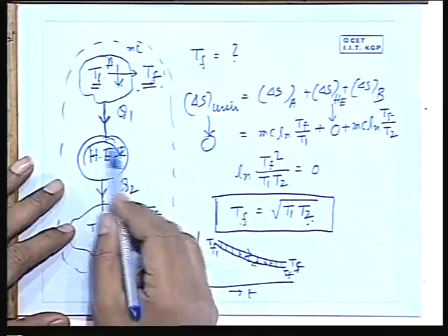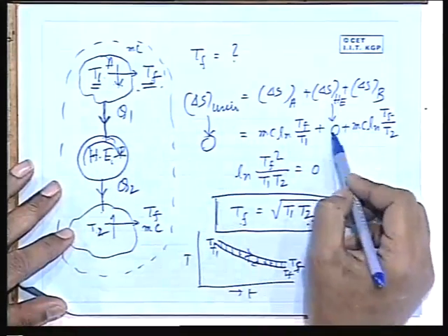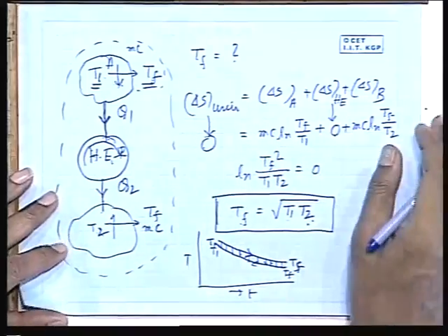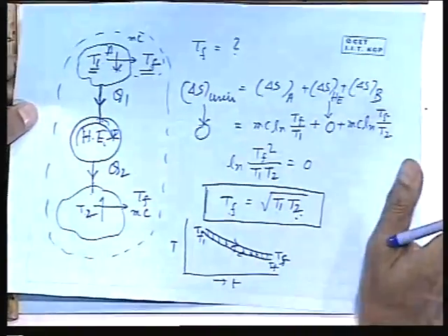You are correct that the heat engine naturally stops. When the heat engine stops, it means it has completed a certain number of thermodynamic cycles. It's not like a mechanical machine; that will be clear again afterwards. If it is stopped at any point and has not completed a cycle, there is a net displacement left. It is not like that mechanics thing. So it is always executing a thermodynamic cycle. So long as work is there, it has to undergo a thermodynamic cycle. You have understood? So there has to be a thermodynamic cycle always, so that delta S of the heat engine is 0. Good, I appreciate your questions. Okay, then it is all right, please.